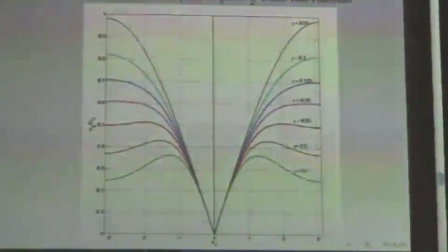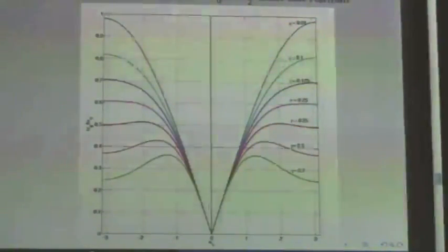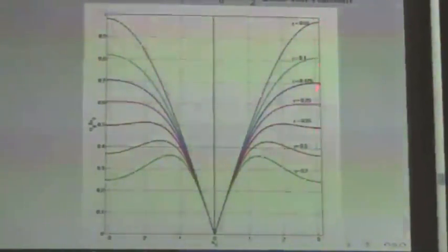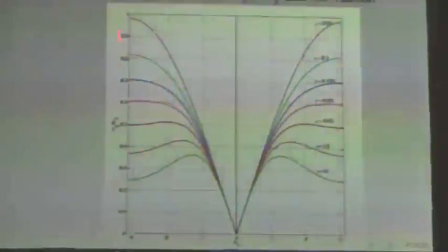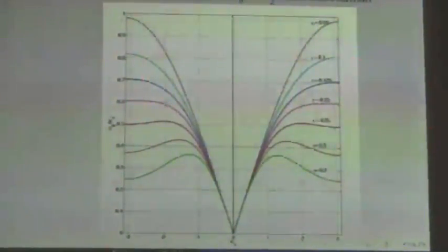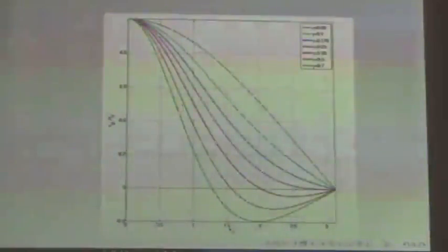It's also clear because the characteristic function is a function of sine square, and it can be shown that the derivative, always by the chain rule, you see derivatives on the borders is always 0. So you have all these necessary conditions of a lattice model automatically included, and you always have elastic stability of your lattice model as well as of your continuum model.